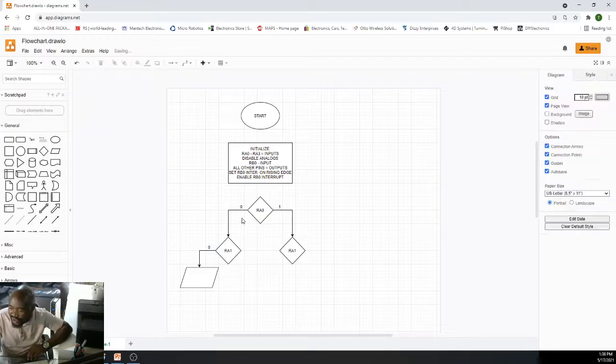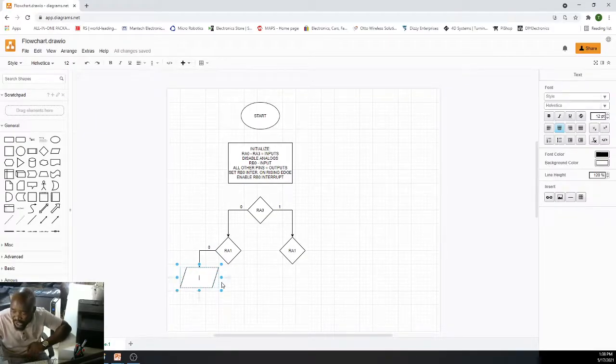So when we get 0 and 0, what is supposed to be our output in terms of the exclusive OR? And then remember the output is on RB2. So our RB2 must be off, must be low, because the two inputs are both zeros. 0 exclusive or 0, you get a 0.